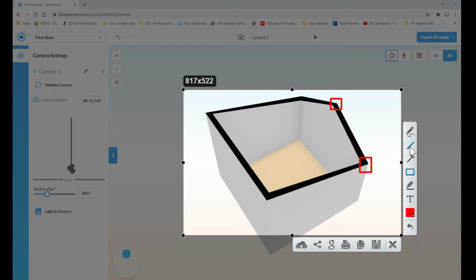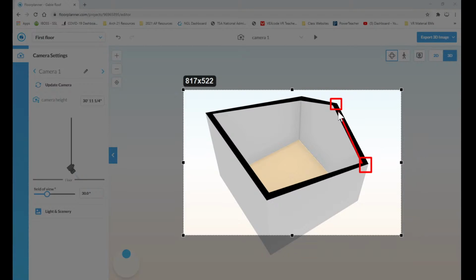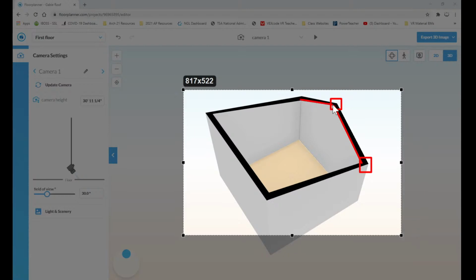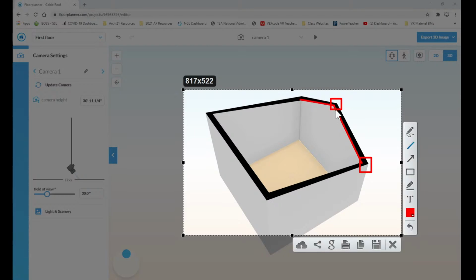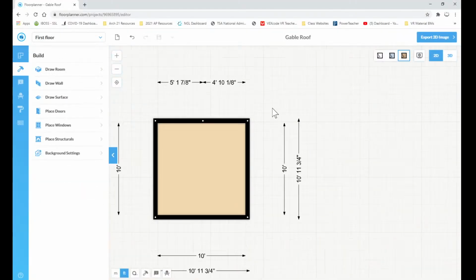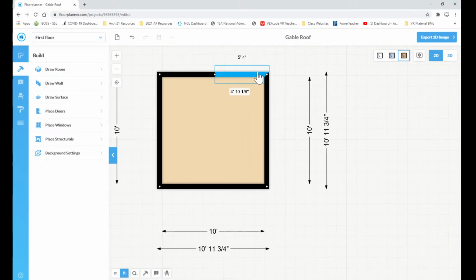Okay, and so once again we created 2 walls. We created one that was here with 2 different heights at the ends, and then we created another wall, the same 2 different heights at the ends, and then they connected, and then we have a gable peak. So we're going to do this to the other side, and this is the repeat. As you can see, when I put my mouse over, I have 1 point, another point, and another point, because this is one half of the wall and this is the other. They're 2 separate walls with their pairs of measurements we just discussed.